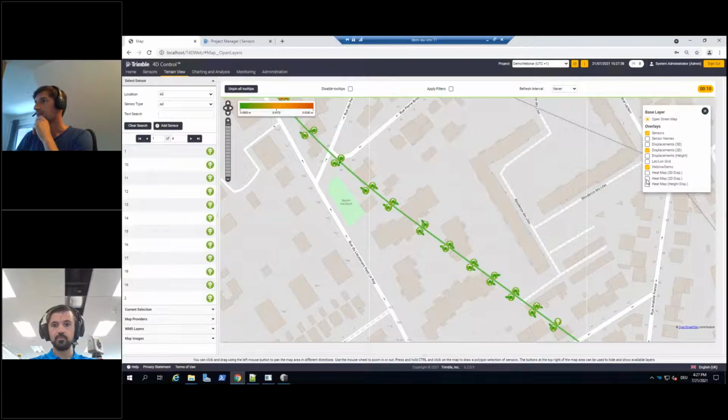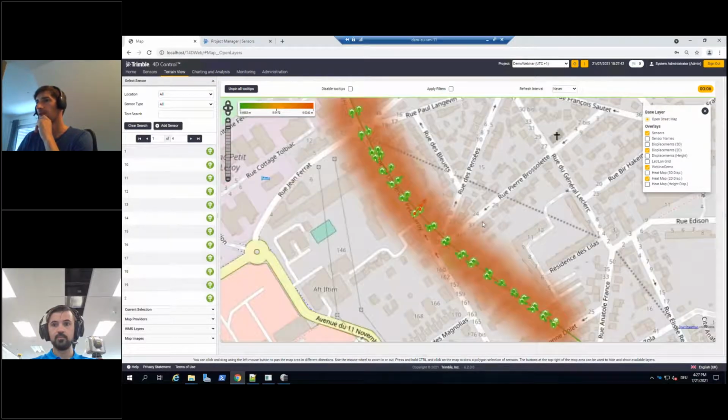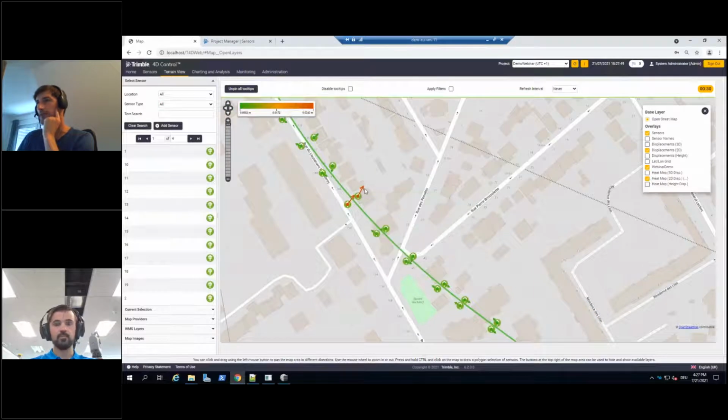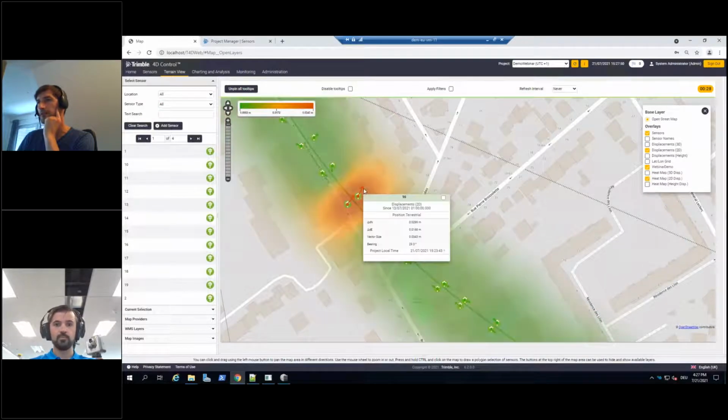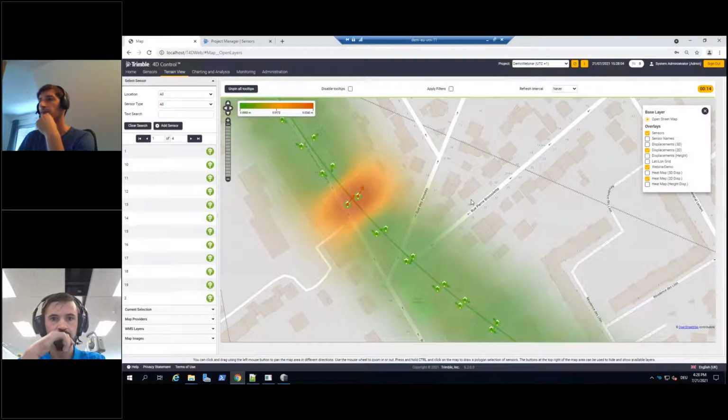What else can you do? You can, for example, enable a heat map, a 2D heat map. So here you see this in red, so I have an alarm here, or I got an alarm earlier because there was some movement. For example, the vector size is 3.5 centimeters almost. Delta offset is 3.2 centimeters, so that's why it is red.